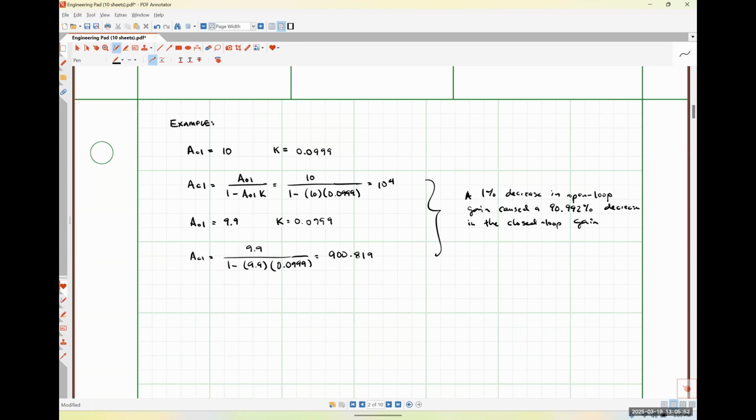In a lot of applications, that is a very bad thing. However, that is actually exactly how electronic oscillators work. So we're going to talk about what's called an astable multivibrator circuit at the end of this class meeting. That's the last circuit that we're going to look at. And it effectively has no input signal whatsoever, but we will see that depending on the values of the capacitors and the resistors that we use to bias our op-amp network, we can generate clock signals.